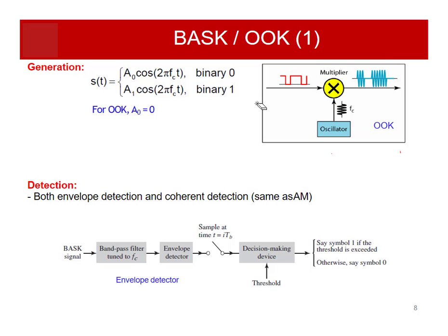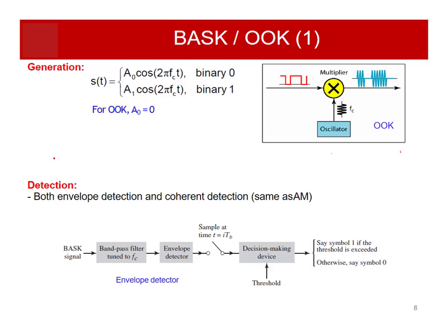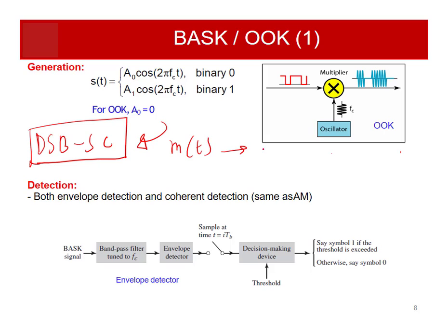How do we know that? Remember the block diagram of SSB or DSB-SC modulation technique, double sideband suppressed carrier. In this case, our modulation scheme was very simple. It was something like this. This was our modulation scheme for DSB-SC: the message signal is multiplied by the carrier signal, and that's all for the DSB-SC modulator circuit.